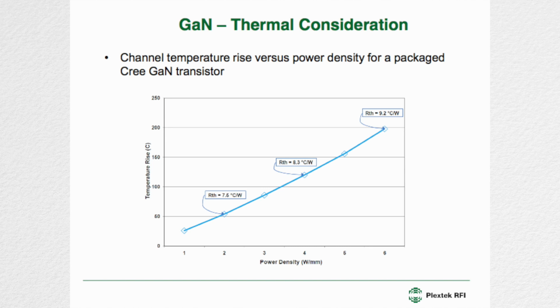So this is the next example we're going to look at. This is a 15 gigahertz PA for line of sight links. Cree's quarter micron GaN process. We're optimizing for IP3. We're going to put a complex modulated spectrum through this. So we need to ensure that we preserve modulation fidelity.